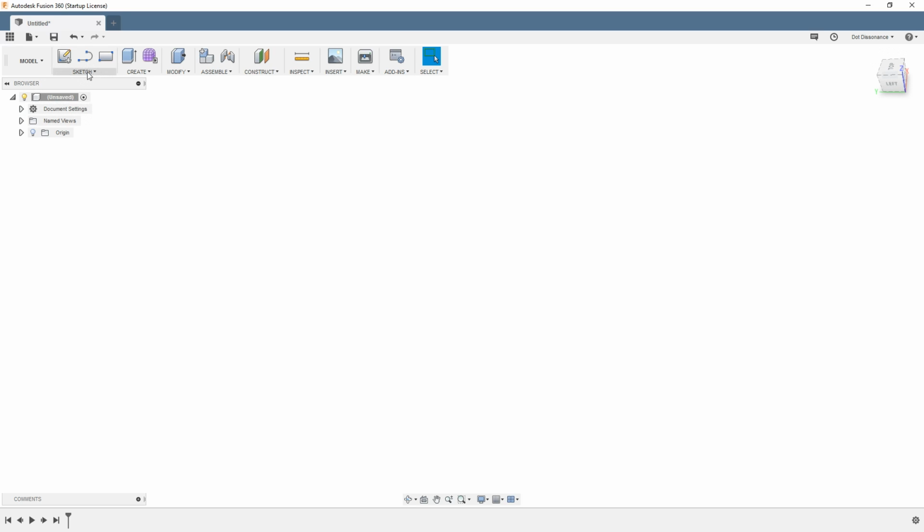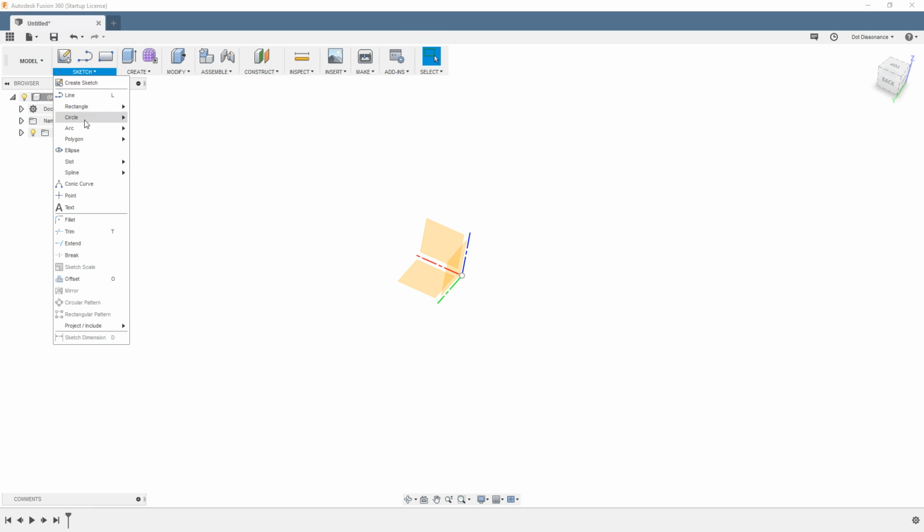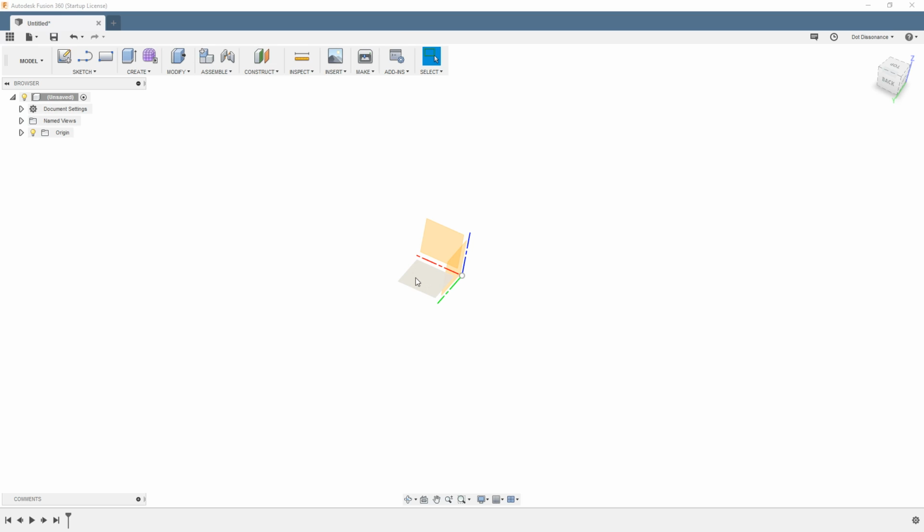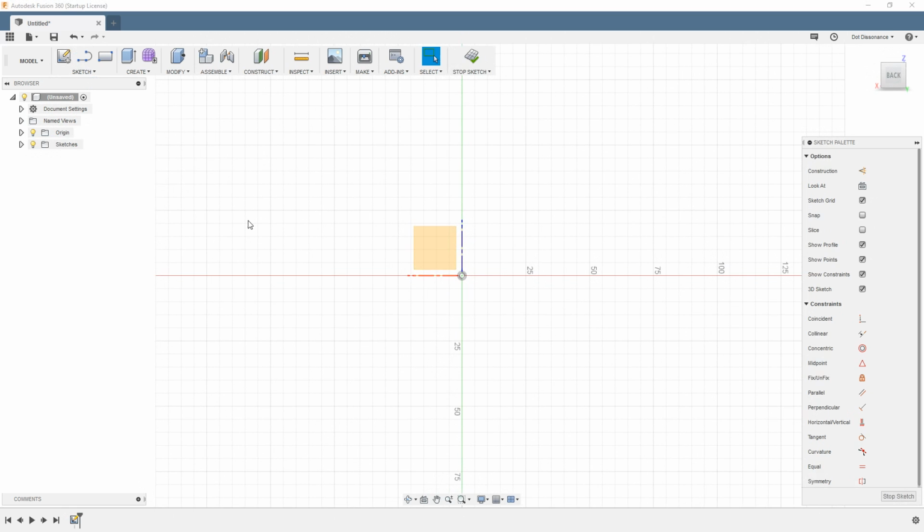So let's go ahead and unhide that, just to show you that before, first, we hit this button, right? Create sketch, picked a plane. Then we said, just make a line, ask for plane, everything we just did, right? You can also come over and pick an object first and then go do that thing to that thing that you selected, right? So I can hit this plane here and then I can go into sketch, and now I'm into sketch that way.